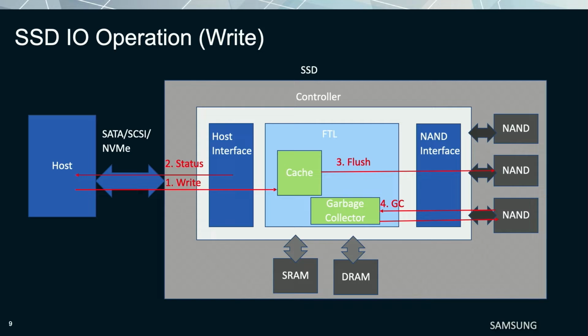So if you take the SSD controller, these are the two cores, host interface and NAND interface, okay? And in between the software is running as FTL. I mean, I'm talking about some particular device. These cores may increase, may change. So based on the vendor, some vendors make this controller with 3 cores, 4 cores also to manage. As the NAND density increases and NAND speed increases, you need more cores to handle this, right?